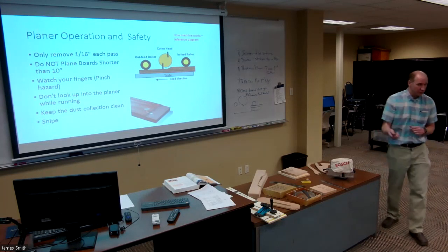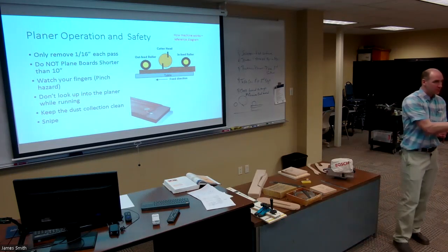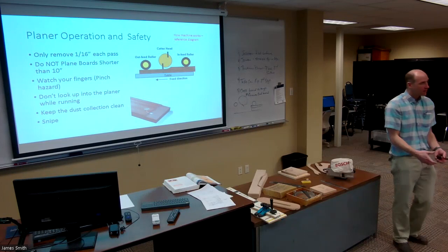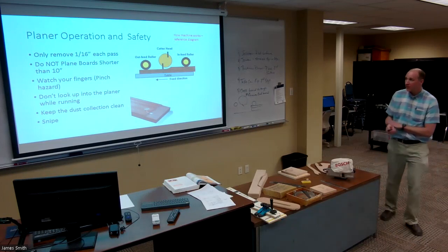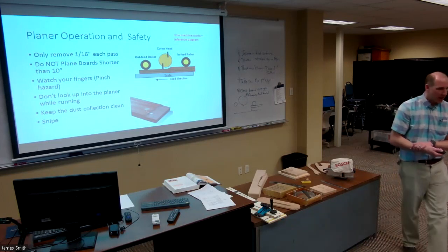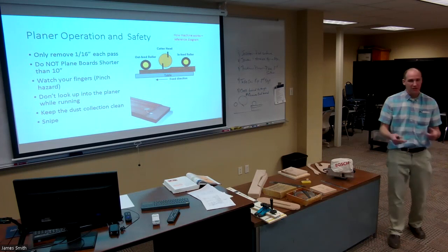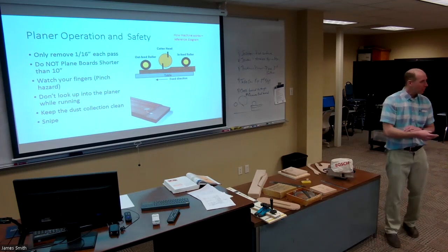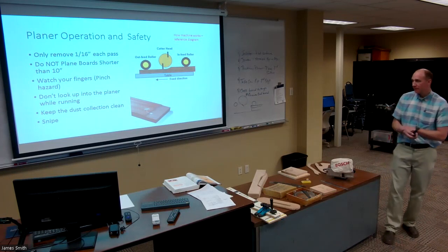The other thing too, watch your fingers. Okay, when that pressure roller grabs that board and starts pulling it in, it wants to snap that down. So don't ever hold your fingers underneath the board and get your fingers pinched that way. Look up into the planer. This is a messy process, you guys. It creates a lot of chips, so always make sure that your dust collection is turned on, or do it in an area where you can handle a lot of mess. It's really messy that way.